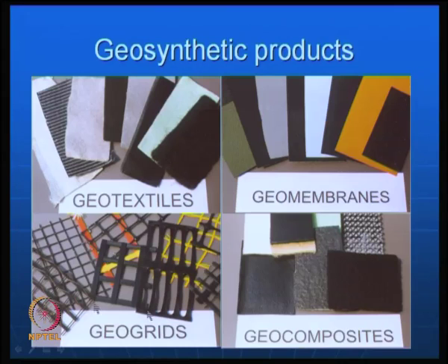So, geogrids are all plastic materials, made of high density polyethylene, PVC, polyamides and all that. Geogrids are very good for increasing bearing capacity, reduction of settlements, liquefaction resistance and all that. Geotextiles are very good for drainage, separation and wherever protection layers are needed.